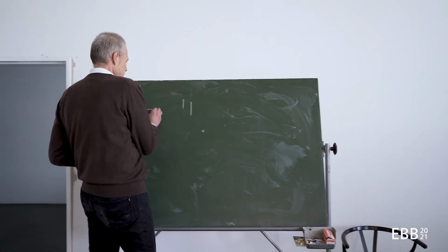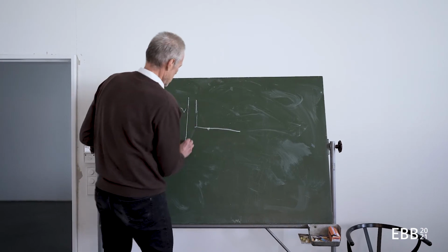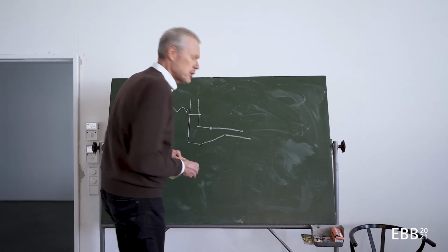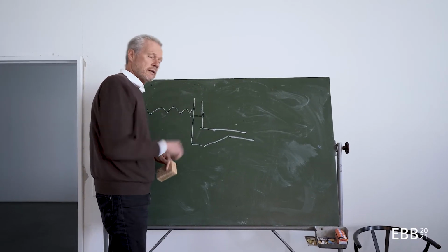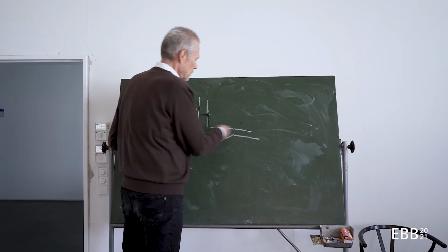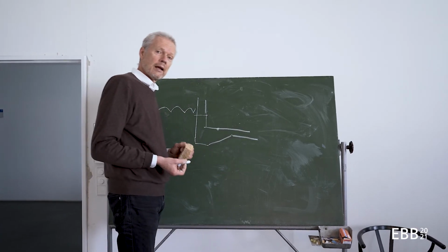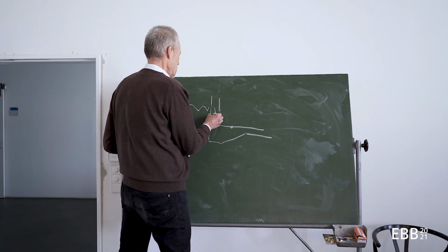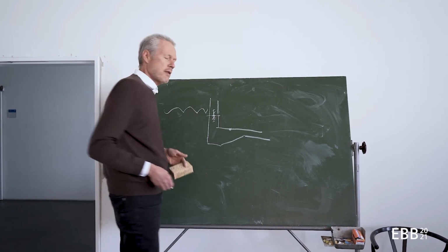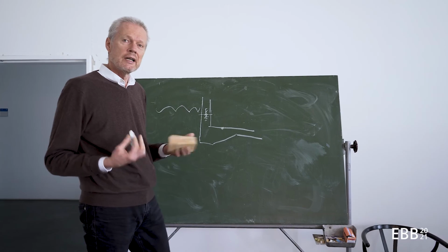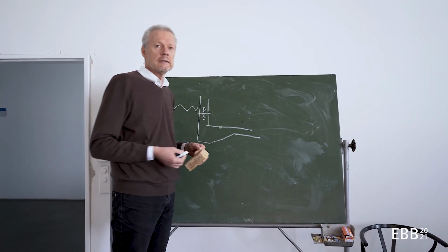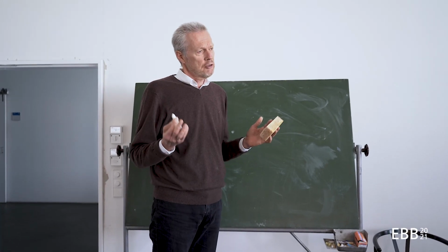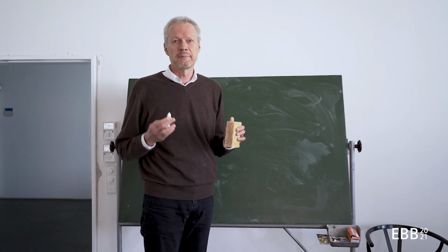So for example, if I have groundwater, it might be necessary to create a continuity between a vertical concrete wall and a horizontal concrete base plate, and then this continuity here has to be assured with the special jointage that we will discuss in another conference. Load transmission, I think